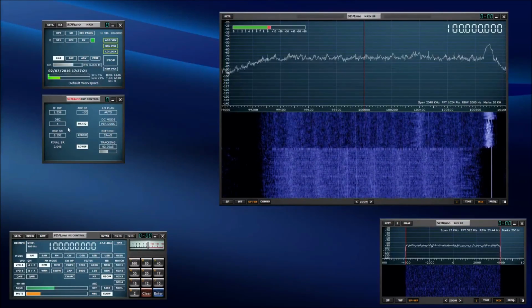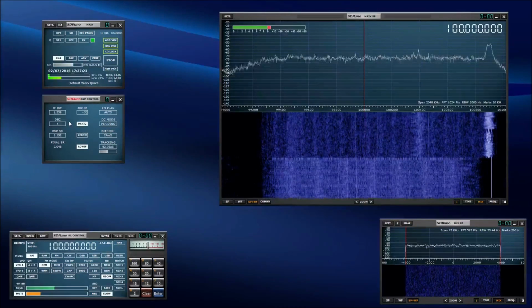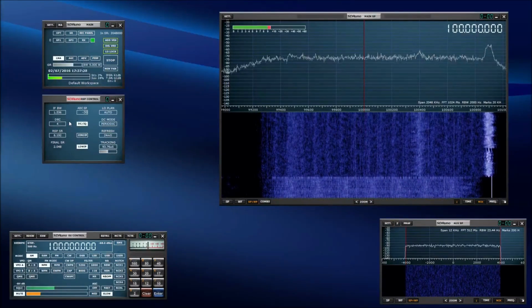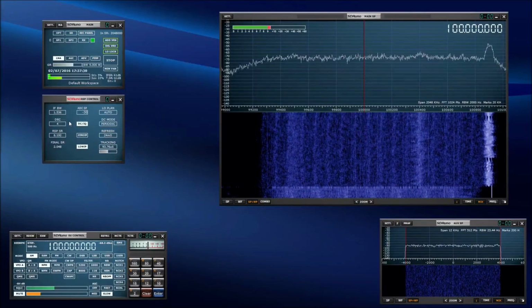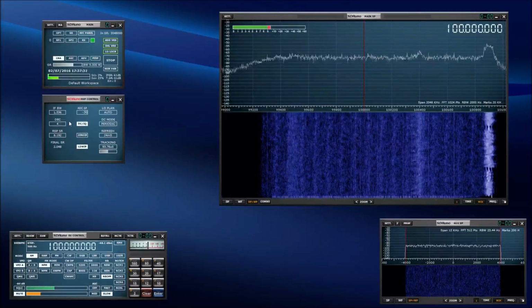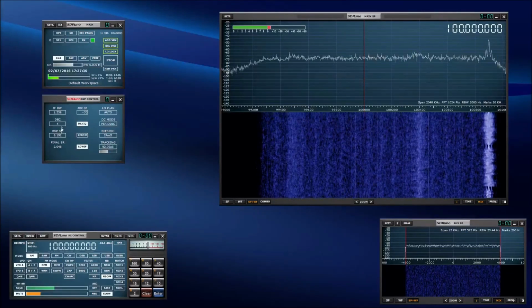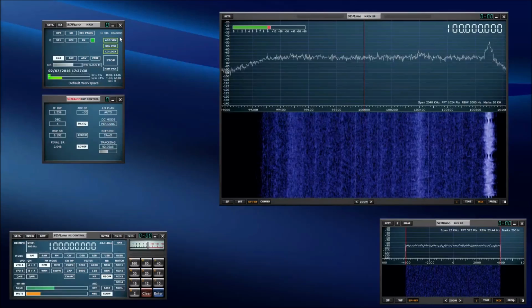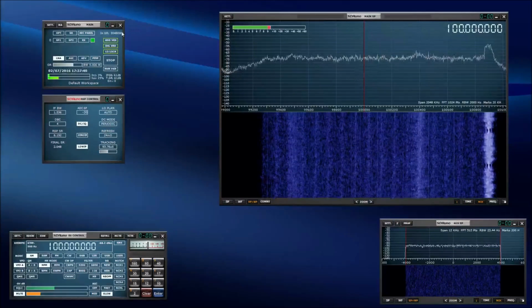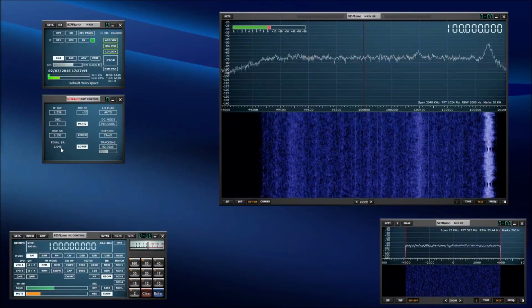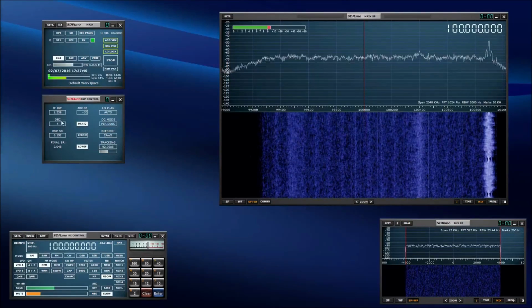And we've now got this new API that we'll be releasing very soon, where we now support decimation. So we can get better performance by specifying higher sample rates. We use decimation such that the final sample rate that SDRuno sees is actually 2 megahertz, but you will get better performance with this.